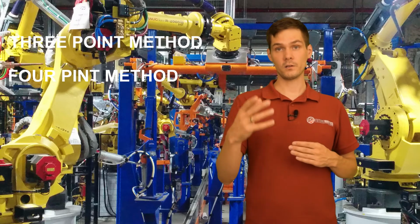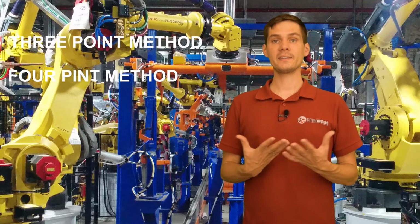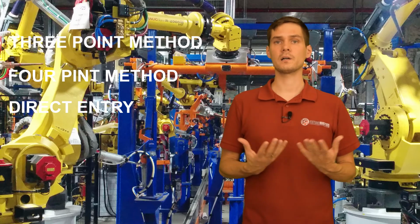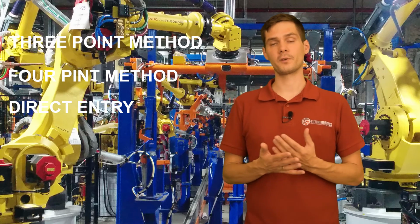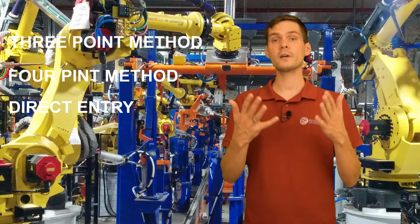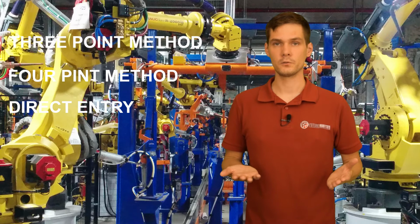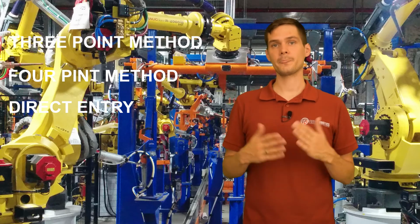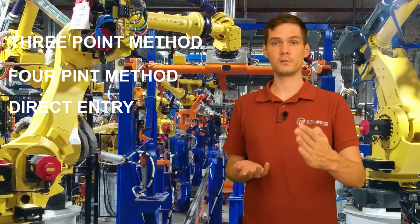You will see it better when I do it in the RoboGuide. And the last one is, of course, the direct entry. And that's the one when you get the measurements from, for example, a measuring team. They measure the frame, or you get it from the CAD data from the model that you've got from your designers. So you can type it in, and there you go. There you have your user frame.